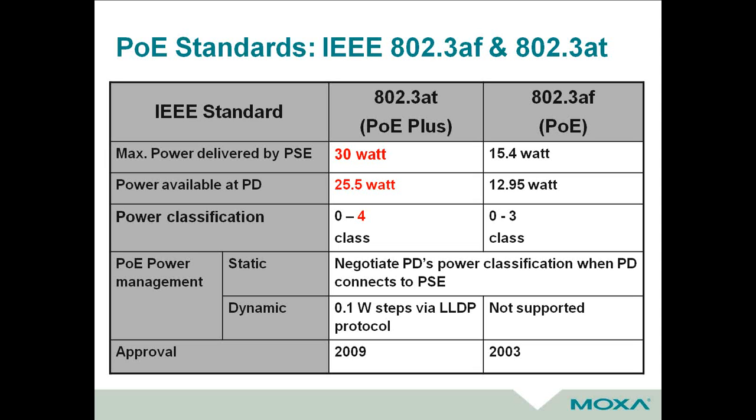So yes, PoE standard is 48 volt DC, not 24. And we're looking at a total of 30 watts as a max, but realistically 25.5 is the max that any PD should accept today.